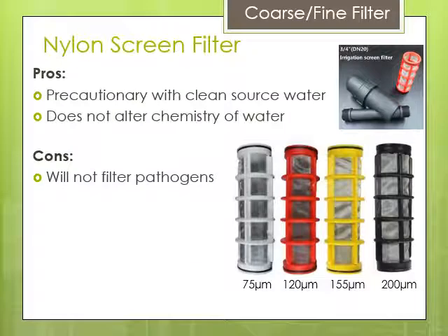These you've seen lots of times around the greenhouse, these screen filters. I'm not going to get into how they work. You open up this cartridge, and inside is the screen filter. They're a bit of a pain to clean because they don't automatically backwash. You have to take the cartridge out, soak it, scrub it, put it back in again. But they don't alter the chemistry, but they definitely do not filter pathogens.